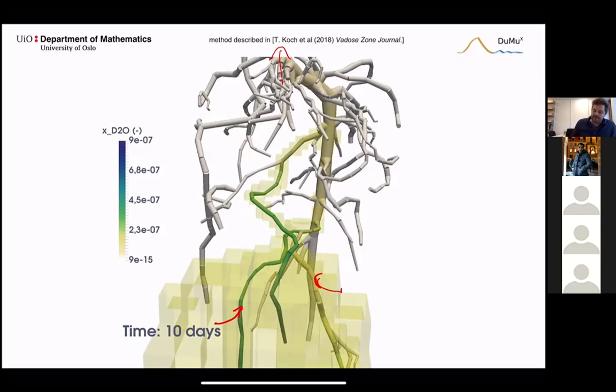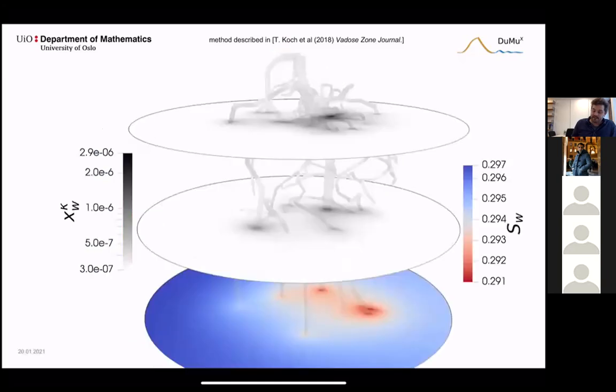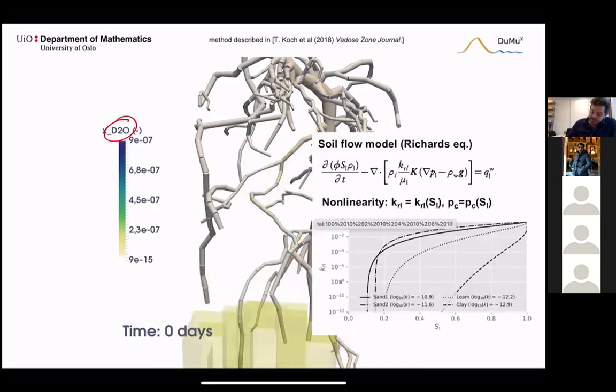We looked at this simulation for a while, and we realized that actually for these types of root systems, you have another aspect. The relative permeability of your porous medium now depends non-linearly on the saturation. And when you go to very dry soils, this is going to be very difficult for your 1D-3D scheme, because these gradients that we saw before at the vessel, when they now have this logarithmic shape here, get even larger due to this non-linearity, and it becomes very difficult to resolve this.